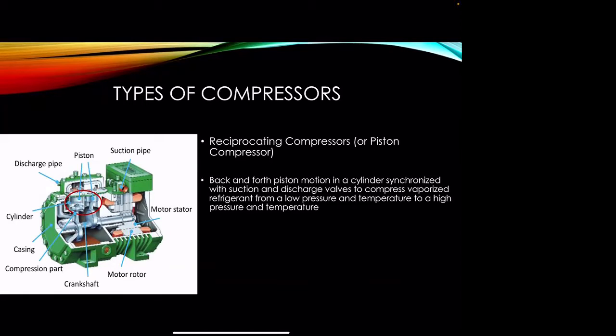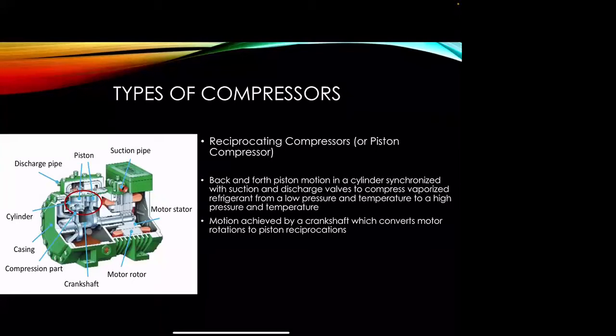You see our suction here, our compression part, to compress vaporized refrigerant from a low pressure and temperature to a high pressure and temperature. The motion is achieved by a crankshaft right here, which converts the motor rotations to piston reciprocations.